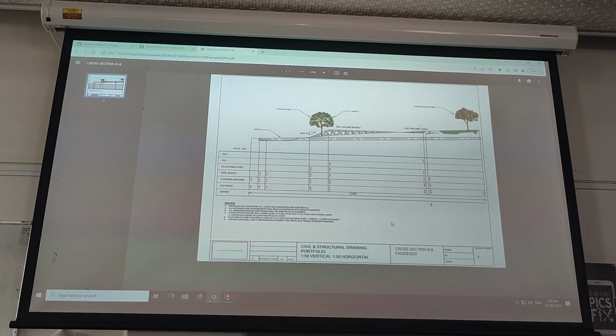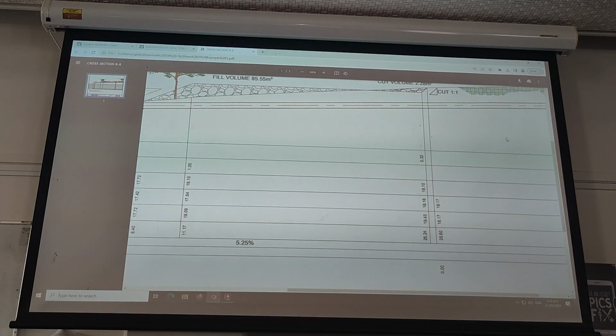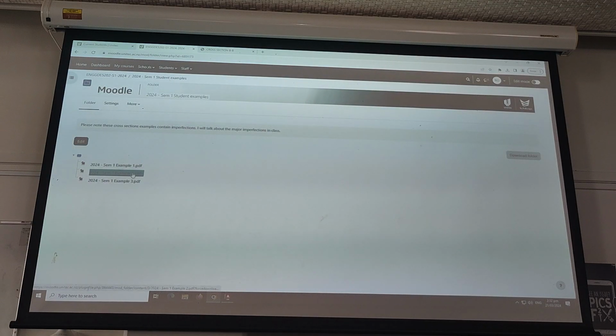So the next example isn't in colour, but it's of a student going a little bit crazy with hatching. And you noticed a little bit of hatching under here. That's kind of all you need. Unfortunately, they weren't listening to Ingrid when she said that it should have been on a 45-degree angle. So they've done a perfect amount of hatching, but yeah, didn't quite get that fella right.